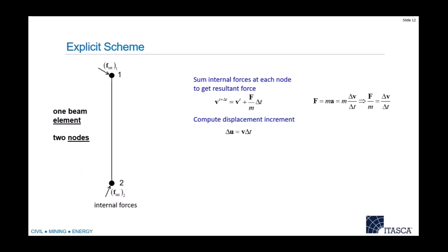And usually, when using structural elements, you're using an element that supports soil, which is much softer. So you might have soil nails made of steel. You might have cables made of steel. Very stiff, very small. So these time steps for structural elements might dominate your whole runtime. It's just something to keep in mind.